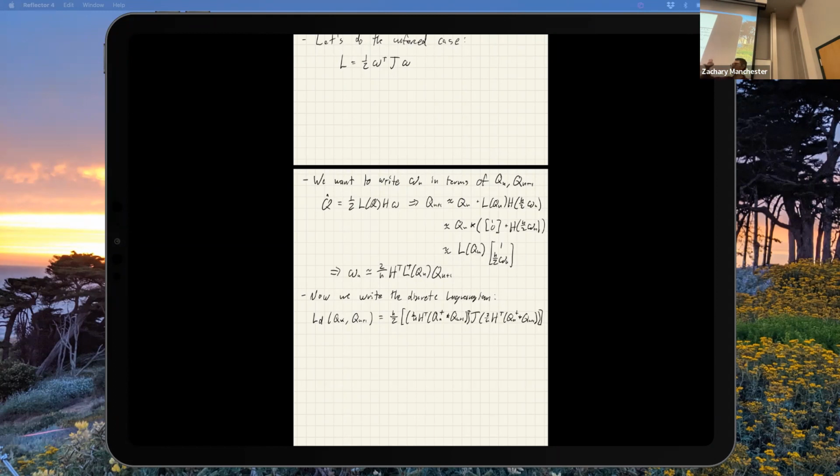So this is the delta rotation between the two time steps, right? So it's an omega thing. You can think of it a couple ways. If I do it this way, I get omega in the body frame. If I do it the other way, I'll get omega expressed in the inertial frame. That'd be kind of interesting to work out for yourselves. There's some ambiguity there. I could imagine doing this in either order. In the position case, it doesn't matter, but here it matters which order I do these things in. Okay, cool. So that's it.